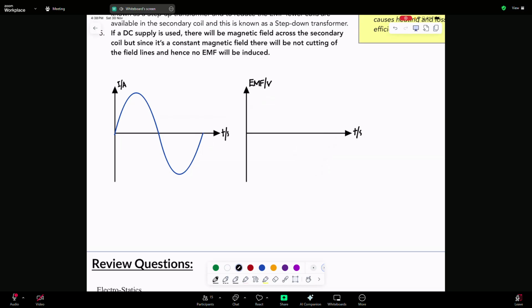To give you more context: our input touches the primary coil, things happen there, and there's an output in the secondary coil. If I observe the input and output and compare them, how do they compare? It could be the same, it could be different, it could be very different. So figure it out. How many waves are there? Let's say 10-10, like it's a 1:1 transformer. The y-axis value is not the concern, we're looking for the shape.